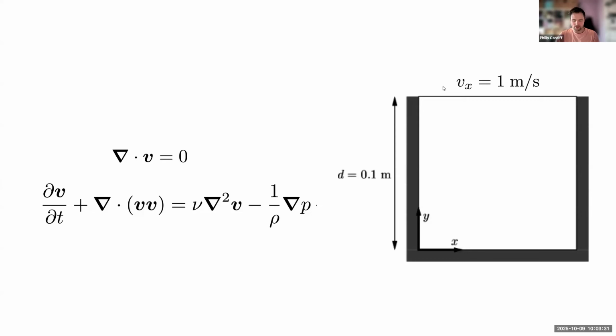So the governing equations in this case, we have just the Navier-Stokes equations, and they're expressed in their incompressible form for a Newtonian fluid. So conservation of mass, which becomes conservation of volume, and we have mass by acceleration and our viscous forces and pressure forces. So the unknowns here are vector velocity U and scalar pressure P.